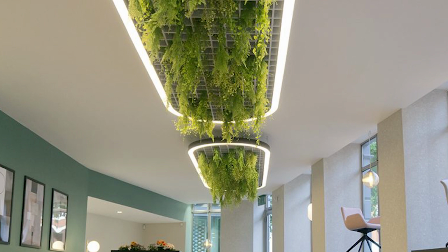The reason that I'm explaining this is because on something like this, it might not necessarily make sense to build the whole thing within Revit families. In fact, when I'm looking at this lighting fixture, I'm assuming that it's a compilation of different things. On one side, this grid element that we see here in the middle, I would build with a slope glazing, basically a horizontal curtain wall system. And then I would do the border.